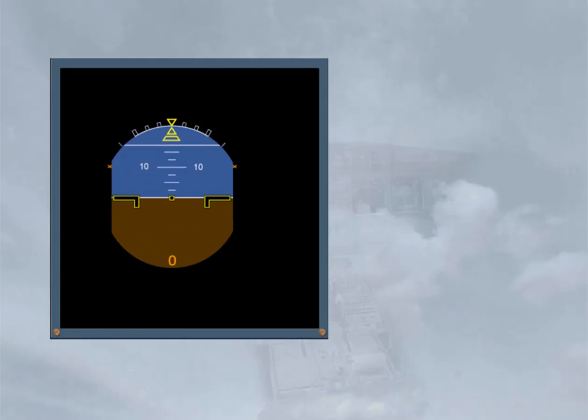Also, after starting the first engine, a white cross shows the sum of side stick orders, and white corners show the max deflection limits. Also, when on ground, or below 30 feet radio altitude, a ground roll guidance command bar is displayed, provided a localizer is tuned. It shows the flight director yaw orders to keep the runway centerline.